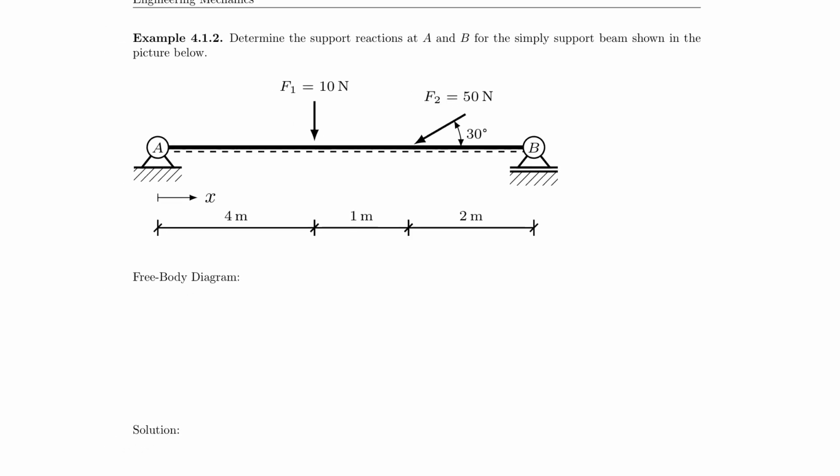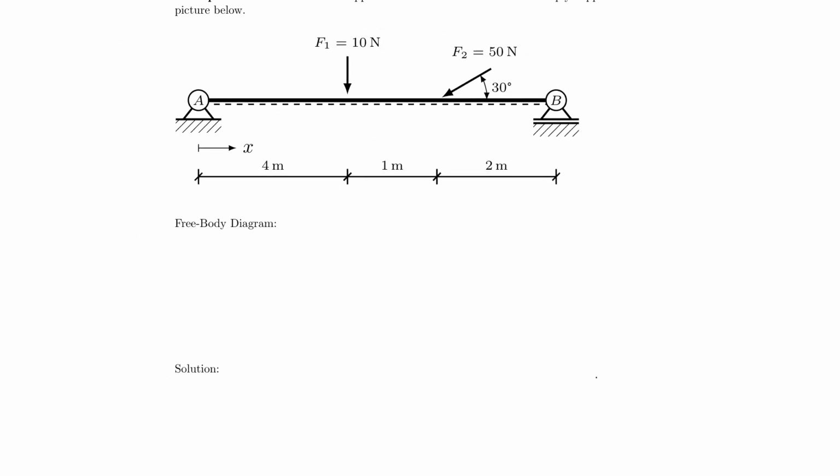And I think that allows us now to draw the free body diagram. So let's go ahead and do that. And of course, again, this is a free body diagram. Therefore, I need to use my dashed line because it is a rigid body. And I have support reactions RAY, in this case RAX.